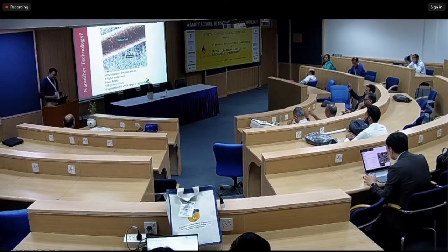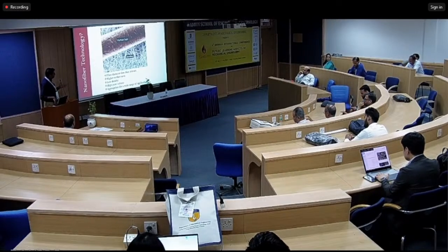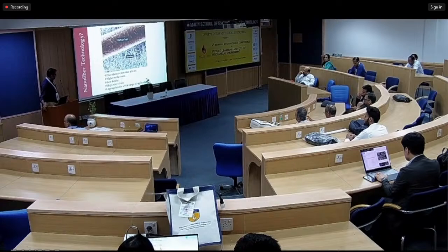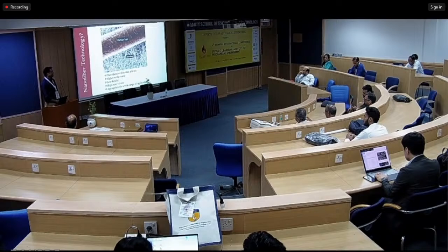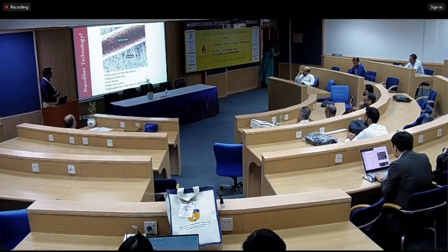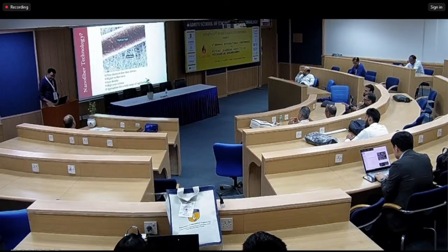So what makes the difference when you scale down? You can see we are able to reach the level where 50 to 100 nanometer fibers can be spun using our technology, that is, electrospun nanofibers. Once you reduce the scale, of course, the surface area is increased and enhanced. Then you get lower density and more surface area exposed to various applications, including air filtration, water filtration, catalysis and biomedical applications.